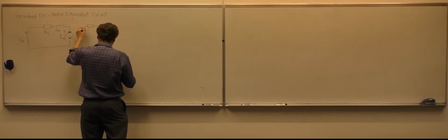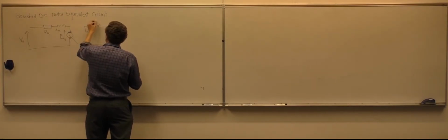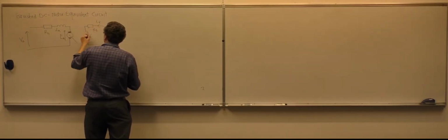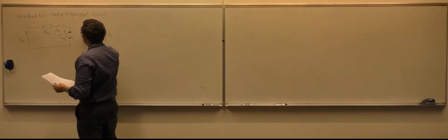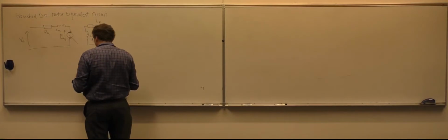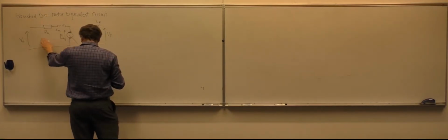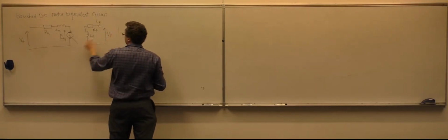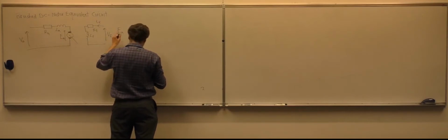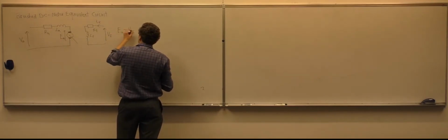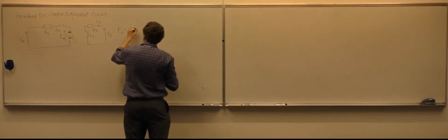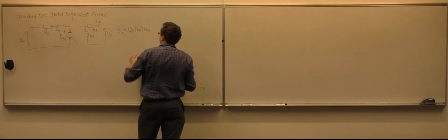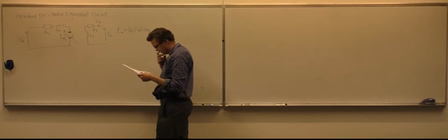For a brushed DC motor, the rotor has a field current on it, and that field current from the rotor then induces a voltage, and so this EA here is a function of the flux created from the rotor, and that flux is a function of the current that you apply, IF, times the rotational frequency that the rotor is going at.